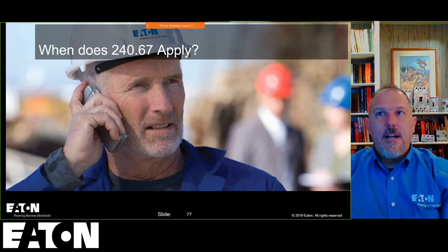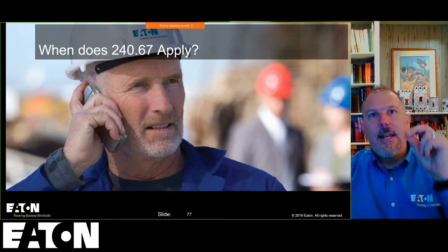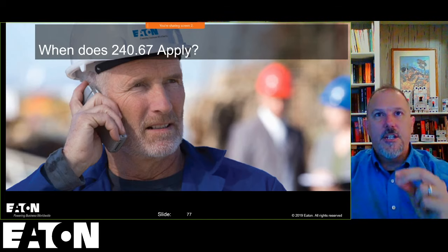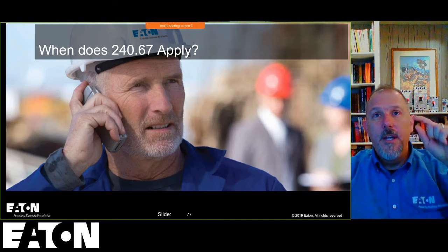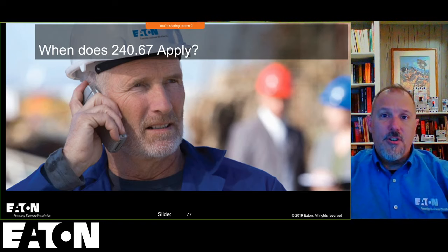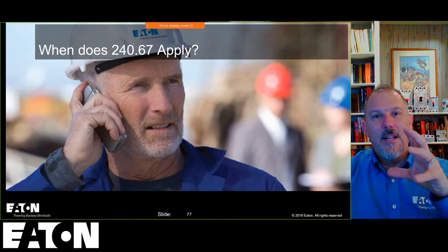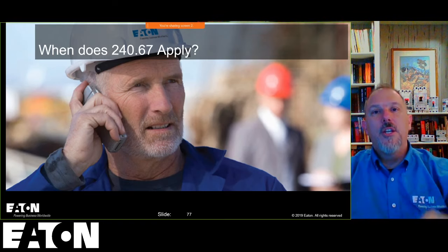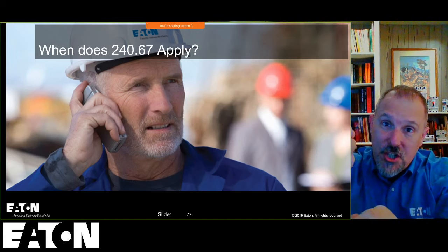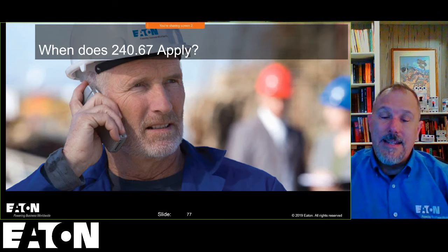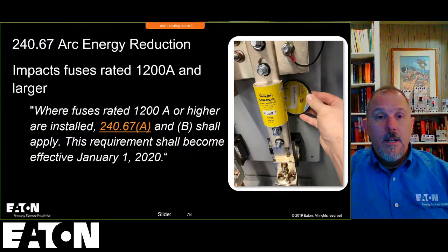Yes, it is not just de-energizing, it is establishing an electrically safe working condition. Roger, you are absolutely right. I looked up and I saw your comment on YouTube. You have to remember, we don't talk about de-energizing it. We have to establish an electrically safe working condition. So that means you have to take that dead front off and you need to measure and assume that it's energized.